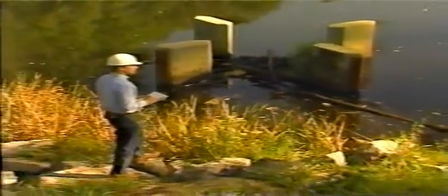Check for slides or signs of slides, such as cracks, scarps, bulges, and leaning or pistol-handled trees. Slide material or other debris can block intake or outlet works, or damage appurtenant structures.